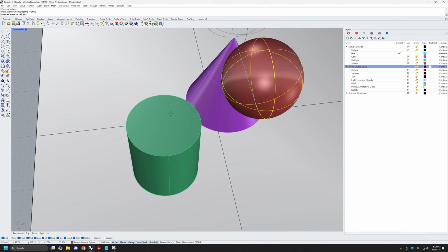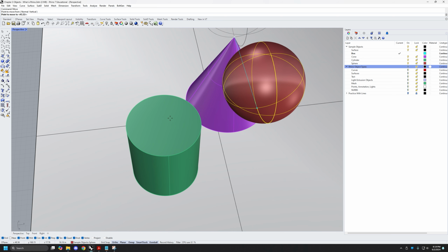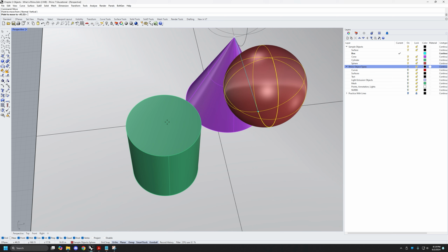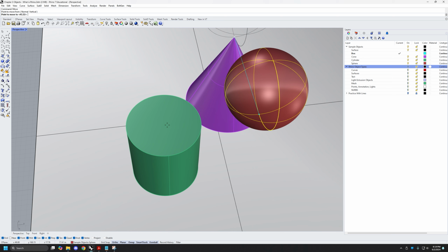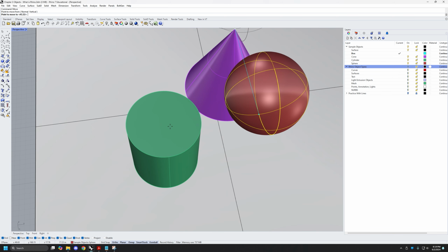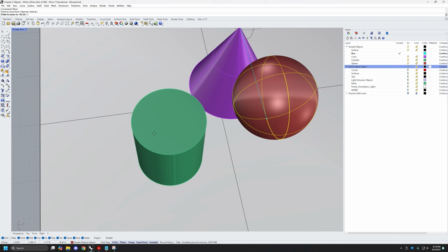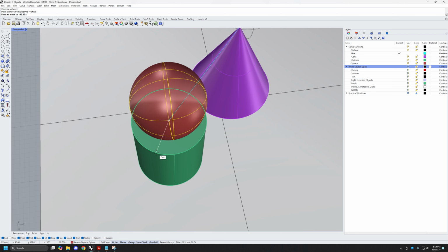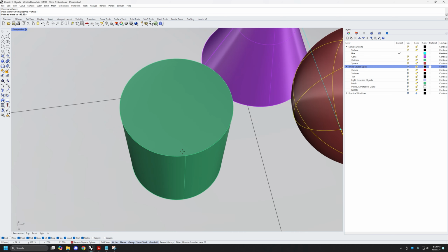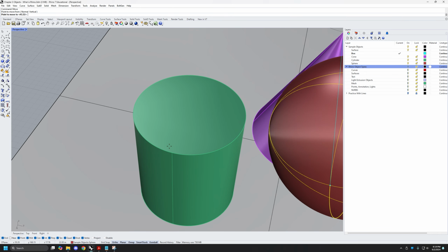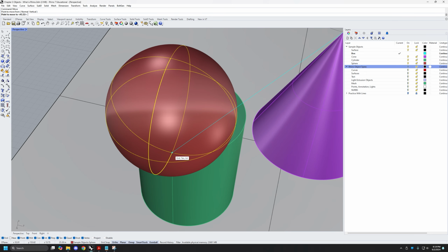The center O snap works by first defining the outer edge of either a circle, a hexagon, a polygon, some other type of shape, it could even be a rectangle, and then it says, okay, the outer boundary has a center at this point. And that's how the O snap works. So it can be a little weird, especially if you're trying to get the center point and it's snapping to this endpoint. You see this end, or in this case, it's end, tangent, intersection. It depends exactly where you're hovering, right? Sometimes you can have these multiple ones.